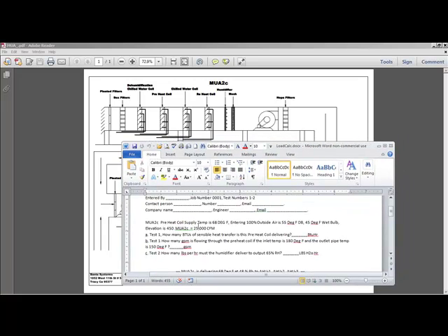So MUA2C preheat coil, supply air temperature. Coming off this preheat coil, we got a supply air temperature of 68 degrees. Our outside air temperature is 55. Our wet bulb is 45. And our elevation is 450, and we're delivering 25,000 CFM. So in our first test, we want to know how many BTUs of sensible heat transfer the preheat coil is delivering